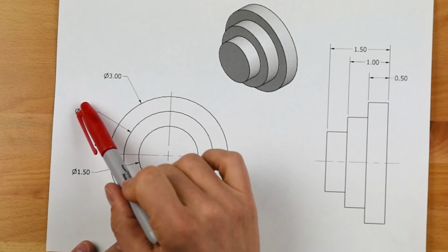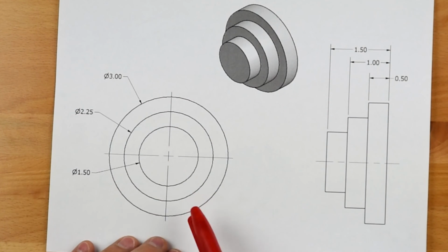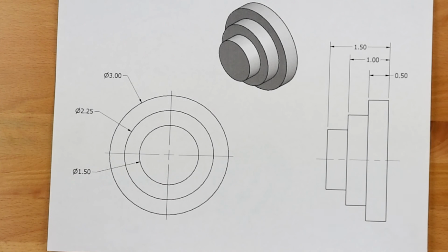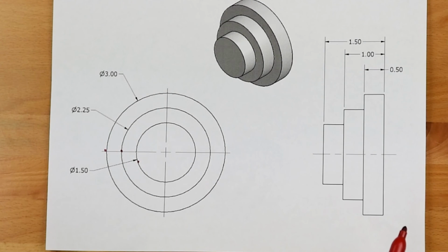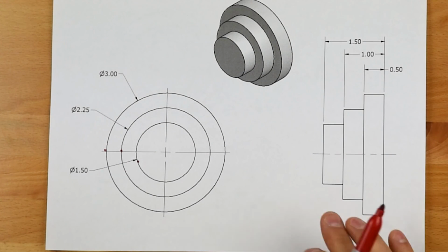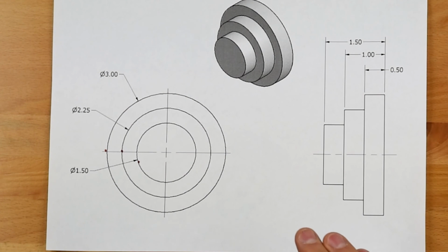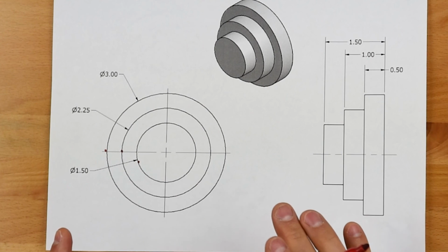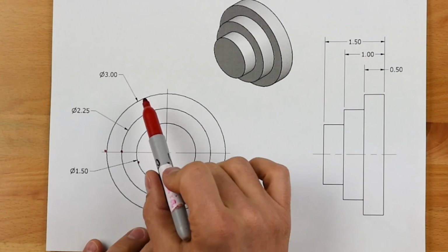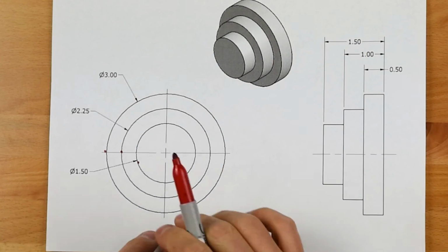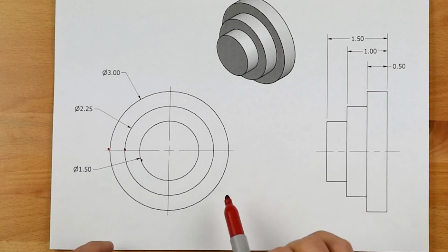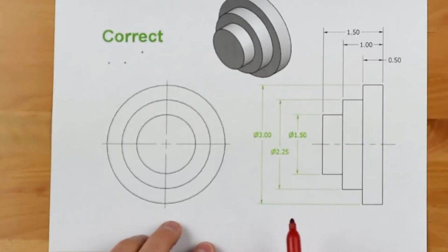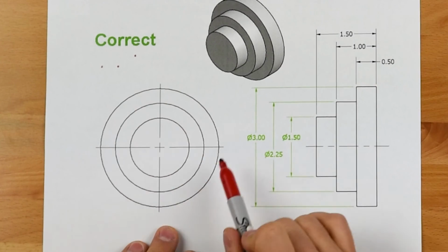And in this case, you can notice it gets to be a little confusing on which one is where. Now these are nice and very equally spaced, and so you could argue on a drawing like this, we don't have too much trouble seeing which diameter those are. But believe me, when you get multiple circles into a hole, it starts to become very challenging to see what's going on. And so when dealing with shafts, now this is not dealing with holes. Holes are different. If these were holes, this is where we would want the dimensions. But since we're dealing with the shaft, what we really are looking for is, again, that idea that we're going to move the dimensions off of here.